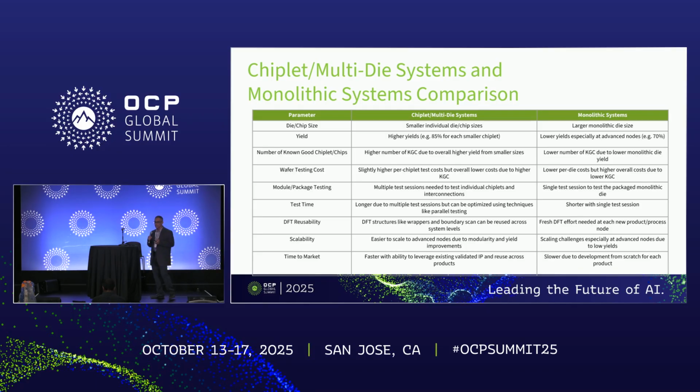So these test insertions will vary depending on which die you are going to integrate on the system, right? Memory die will give some different qualification. Logic die will have different qualification. So as you increase the test insertions, definitely you are going to face more test time,